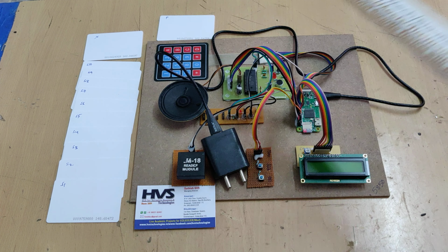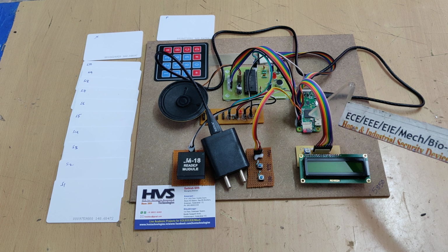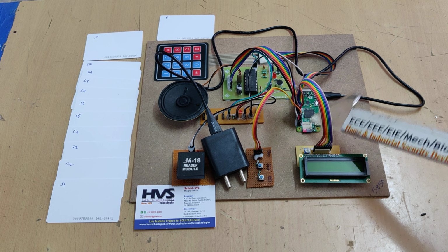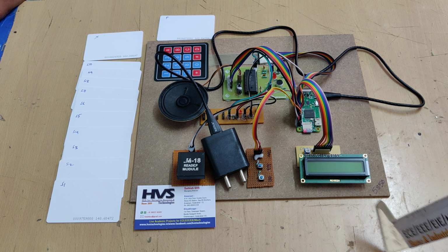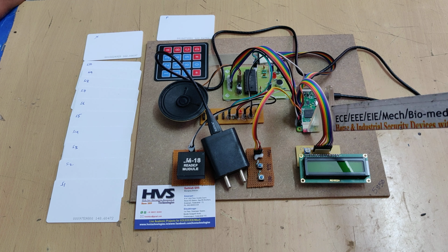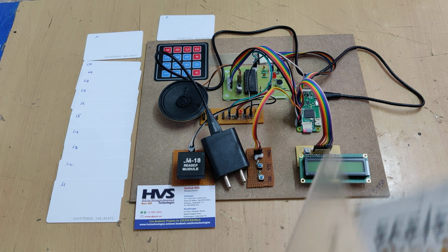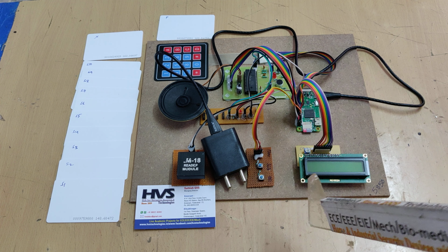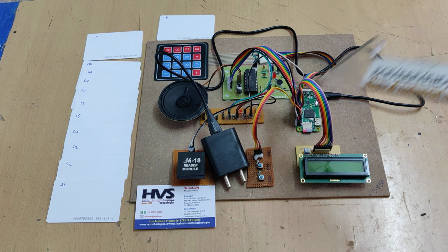So the whole system is run by this Raspberry Pi Zero W and it comes with a 16 GB memory card. Initially, the very first setup is we need to load the Raspbian OS inside this. That's the Buster version OS, and after that we need to install the related modules for the keypad and LCD. After installation of these modules, we need to write the code in Python language for reading the RFID tags and controlling the output modules.